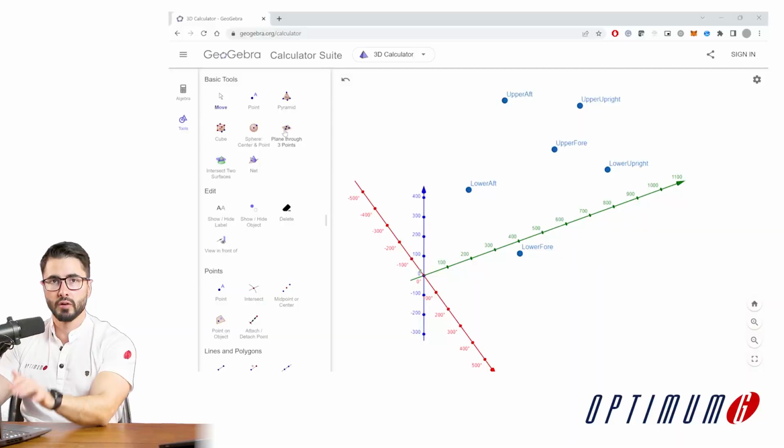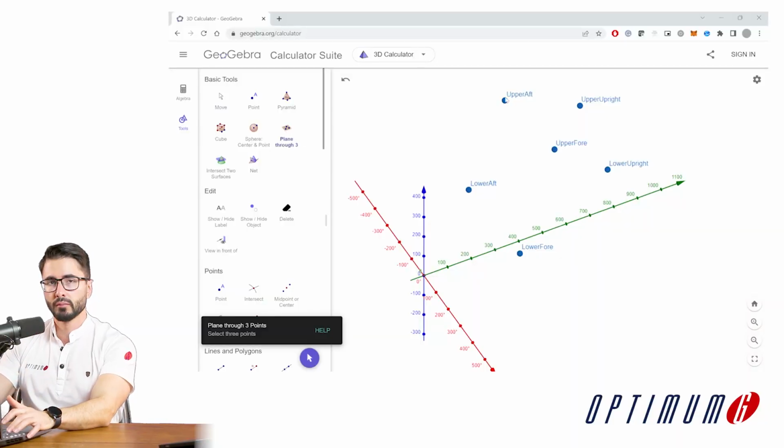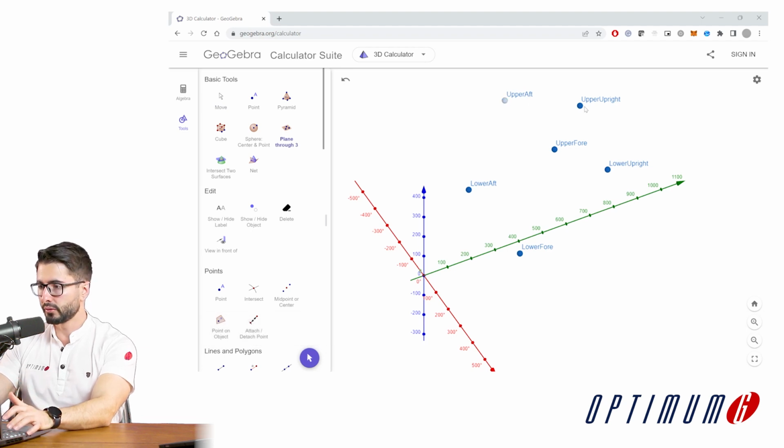So this is what we're going to do. We adjust X and Y as required. We calculate the new Z coordinate to make sure that it is still contained in the same plane. And then we run simulations. We can compare the previous design with the new adjusted version, and confirm that the behavior didn't change much. So let's make these adjustments. We could use a CAD file, for example, or a simpler geometry tool in order to define the planes and find the new pickup points. For the tool that I'll use, I have already defined the pickup points that we found, and I have to define the plane for each wishbone.